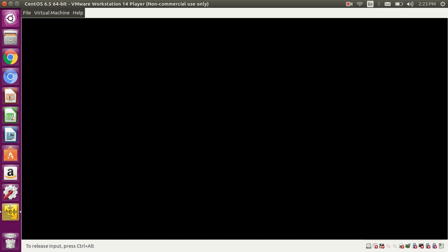But I have explained to them timing is met, and this has to be met with this only. I cannot even change the skew or data path. That's why the insertion delay and skew have not met, but the timing is met. So you have to satisfy him here logically.